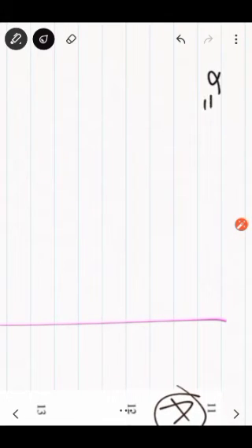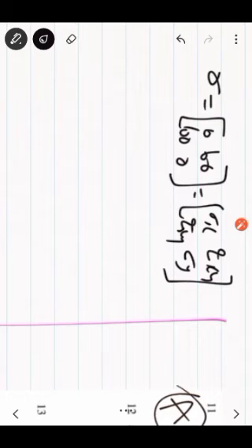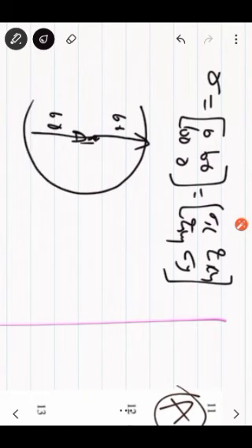So they are given sigma equal to 0 0 60 60. So this is sigma x equal to 0, sigma y equal to 0, tau xy is 60. Okay, so that's what you have given. For the Mohr circle you have to fix a point A, and from there you have to draw sigma x, that is 0, sigma y, that is also 0. You have only tau xy, so this is tau xy, this is above and below. You draw this is 60, this is also 60, and if it is meeting here, you draw a circle of 60 as a radius.